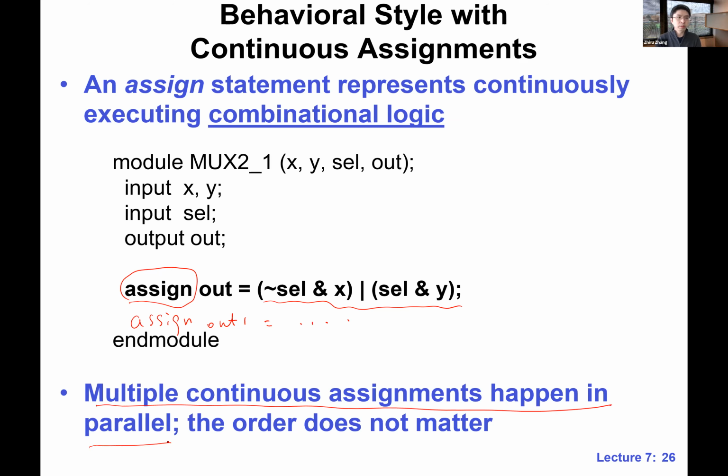So this is very different from writing a software program. When you write things like this, like Verilog, everything is either structural or in parallel. Everything's in parallel. Okay, so the order does not matter.